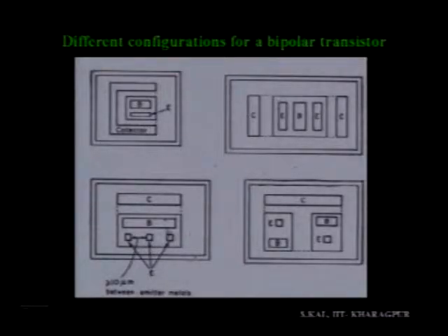Now here the base contact is the same base region, and you are diffusing 3 N region emitters, so you can use it as a one collector, one base, 3 emitter transistor. That is the TTL gate, the first transistor, the input transistors are like that: base 1, one collector, and multiple emitters, multi-emitter transistors. So in those cases this sort of configuration is used.